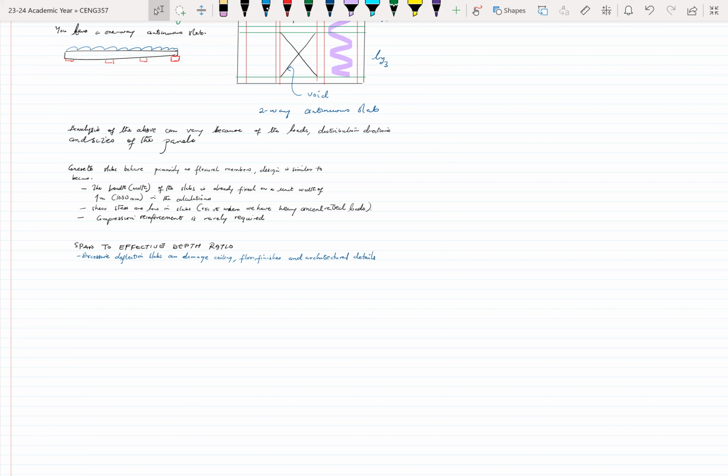All right. So the finishes, even your tiles, right? I think in one of the classes that you guys have seen, the tiles are all bulging up. Maybe it could be a tile issue, or it could also be that the slab itself is deflecting excessively.